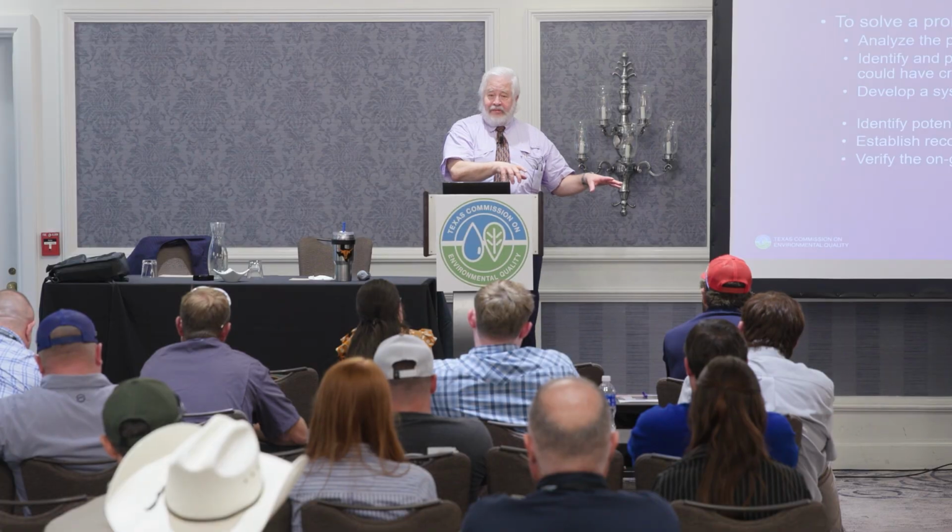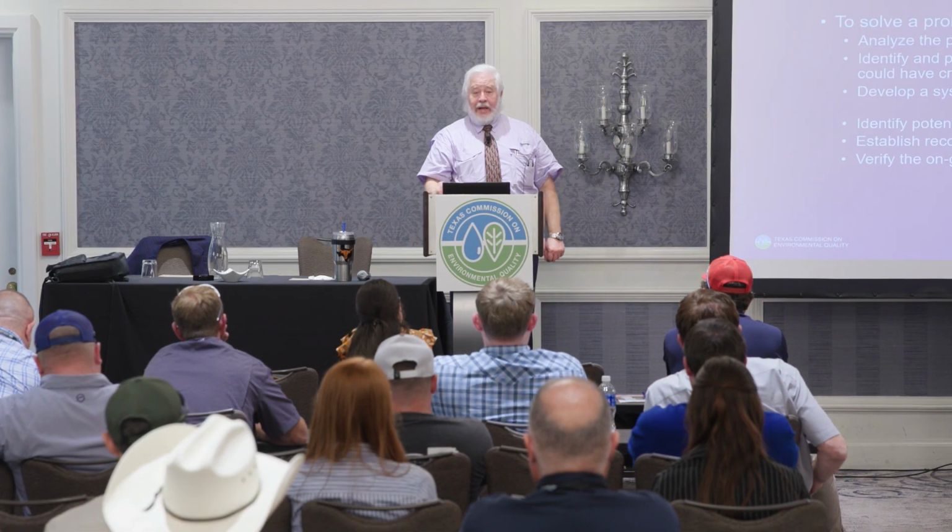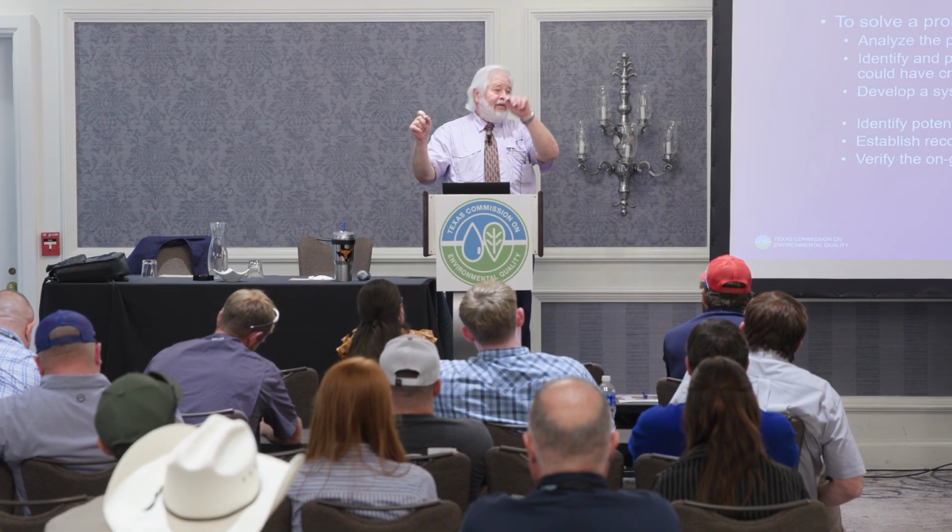When you study a variable, you make a change. 15 minutes later, at a good critical control point, you assess the impact of that change. Then you stop the change, go back to the original setting, and see if things got better or worse when you made the change, and if they return to the previous condition after you undo that change. So I test going forward and I test going back. If you make an incremental change and it improves situations, don't make another incremental change until you verify that the variable that you adjusted is the cause of that incremental improvement.